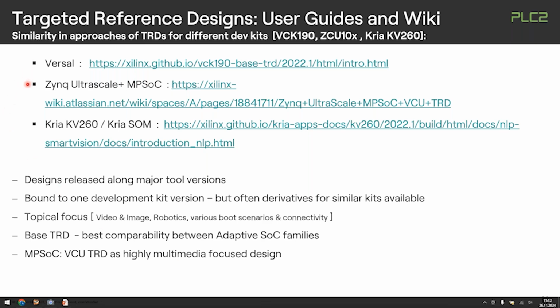Basically, beyond what I said before, I also added the Kria SoCs now, because from a technology perspective, it's really a Zynq Ultrascale device, but from a design perspective, how you approach it and how you deal with it, it's slightly different in the tool chains. But in the end, it's the same topology. So you have this compute part, you have the FPGA part, and you may have additional features like the AI engines in the Versal.